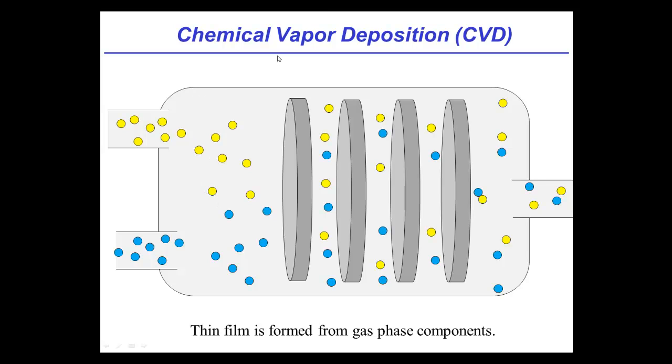It's based on a vapor process, and it's based on chemistry that achieves this deposition. So what determines the methodology behind this? Well, it's affected by the pressure. It's affected by the temperature. The higher the temperature, typically the higher the deposition rate. Similarly, generally, as you increase the pressure, the higher the deposition rate. And the gas flow. And the gas flow is kind of a useful knob, because not only does the gas flow affect the deposition, but we can use it to change the chemistry or the stoichiometry.